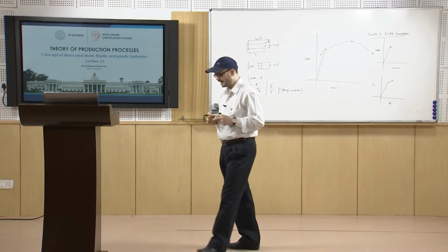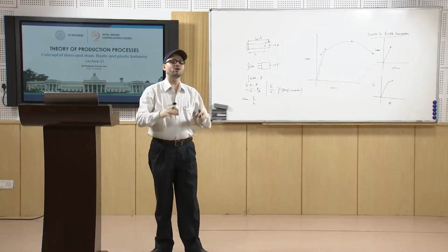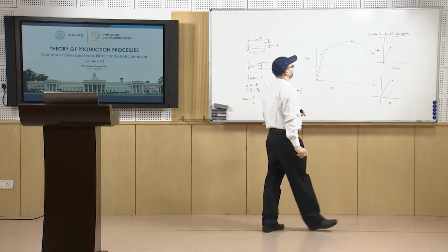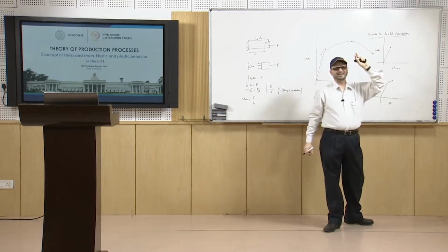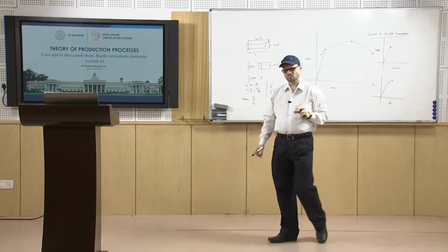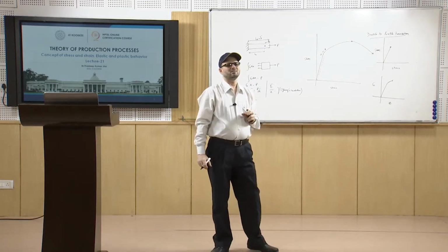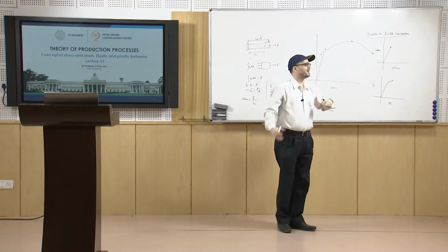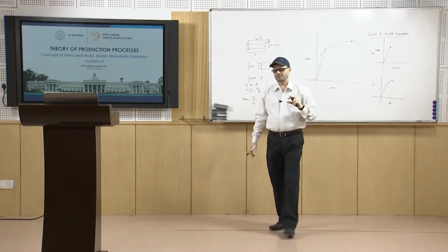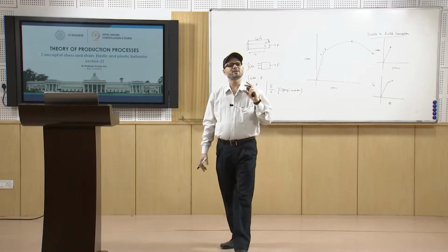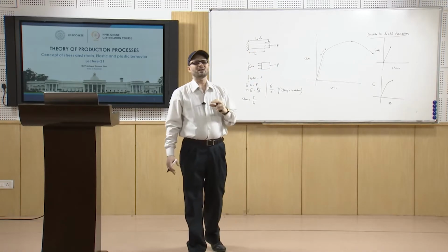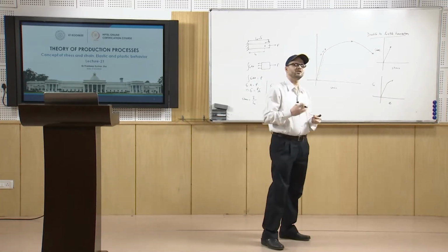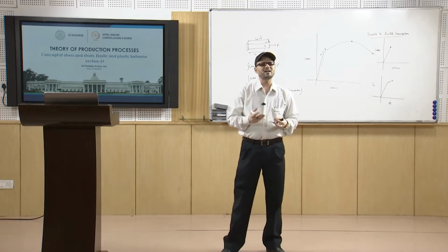So, there are conditions like the type of loading or the temperature, because of which, if there is rapid loading, or if there is very low temperature, even ductile materials like plain carbon steel may behave in a brittle way. So, they may fail in a brittle manner, whereas brittle materials, if the temperature is increased, may fail in a ductile manner.